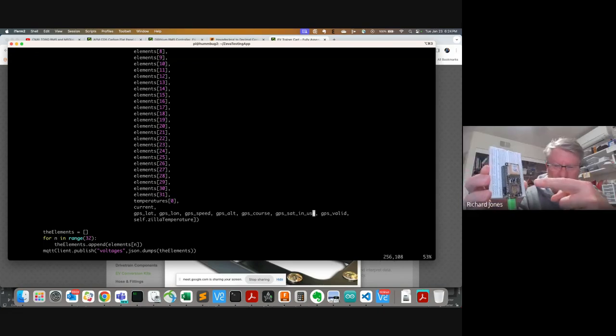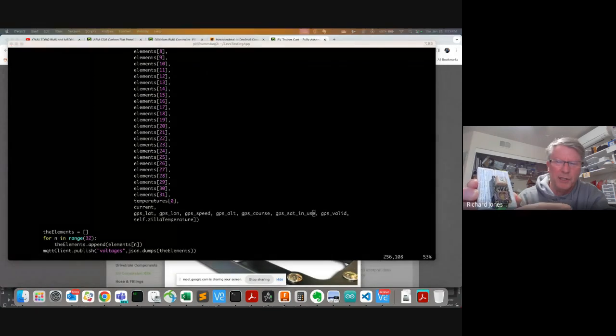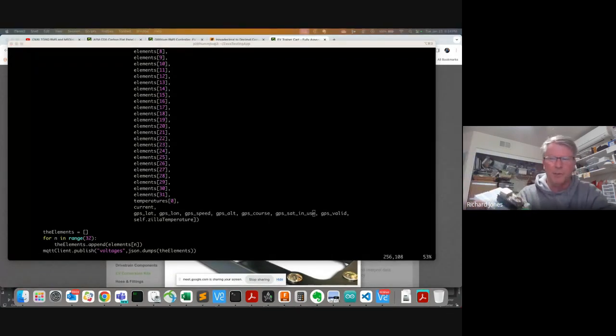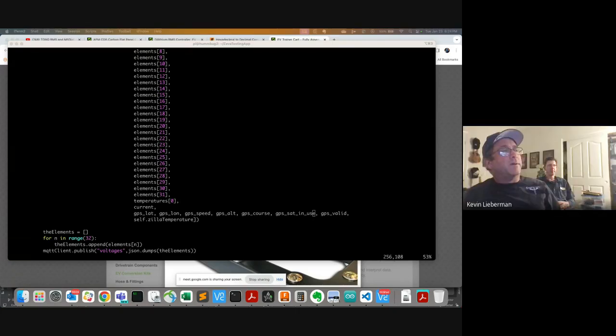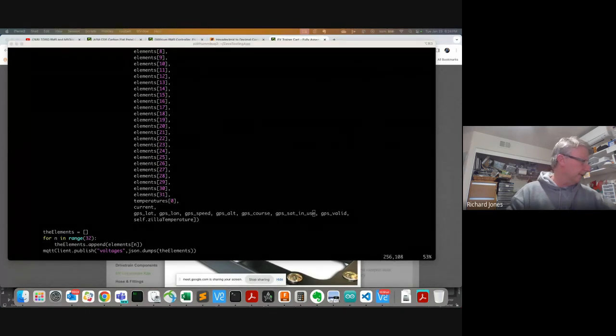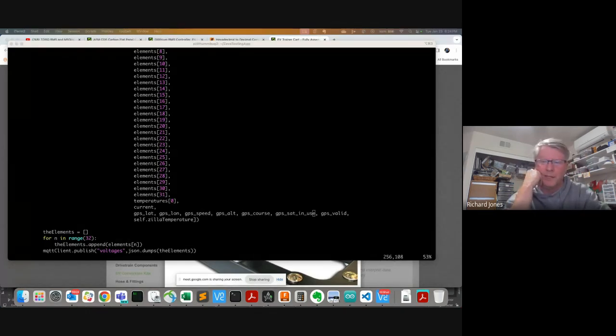And so it's one of my little projects here. This is a $30 Adafruit GPS module that runs on top of an ESP32, another like a $20 box. So this is a potential replacement for the not available or expensive GPS units. Yeah. And then that could send out CAN messages the same as before, and it would end up as a replacement without having to change any software, hopefully. But one of the other little projects I haven't finished.